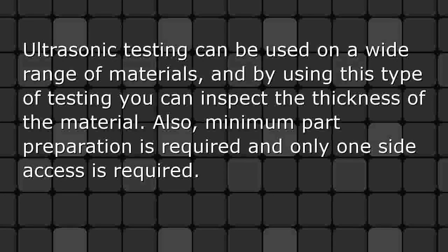Ultrasonic testing: ultrasonic testing can be used on a wide range of materials. And by using this type of testing you can inspect the thickness of the material. Also, minimum part preparation is required and only one side access is required.